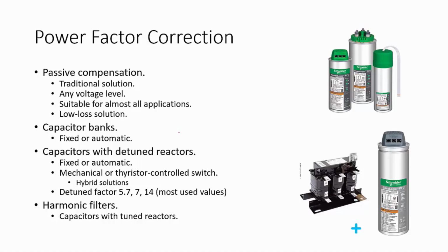Now, when we have very polluted networks with harmonics, which is another major power quality problem, fixed capacitors don't tend to work very well. Automatic capacitors work fine most of the time. But when we have very polluted networks, and by pollution I mean high harmonic content, which comes from electronically controlled devices, PWM motors, transformers, and pretty much any modern machinery, capacitors do not tend to work as well as in traditional systems. But nowadays traditional systems don't exist anymore, because every facility has computers and electronically controlled devices pretty much everywhere.